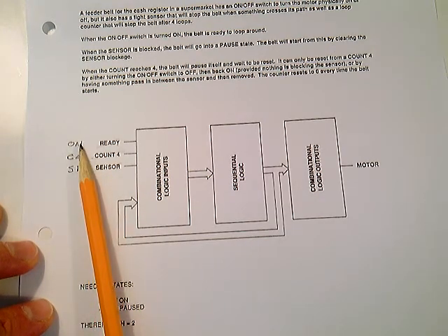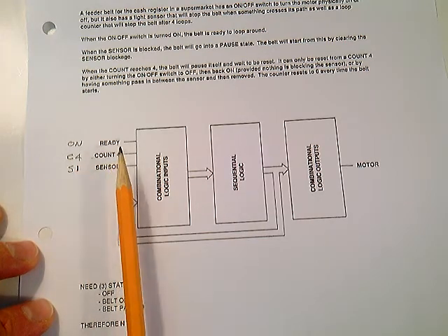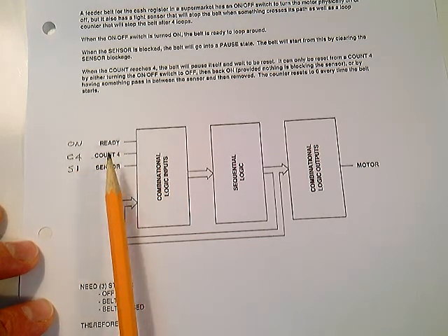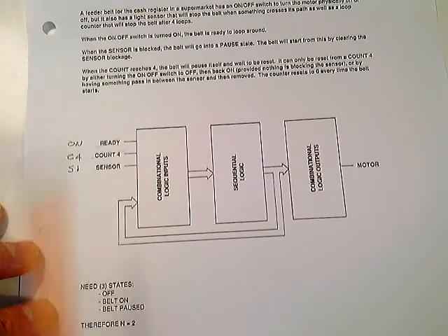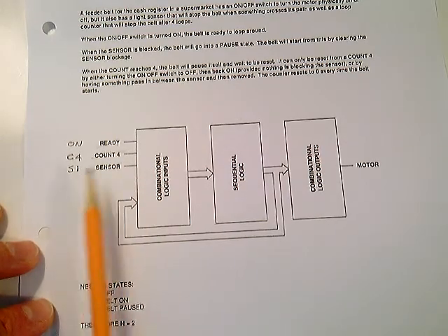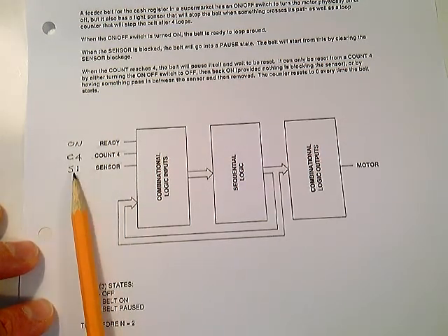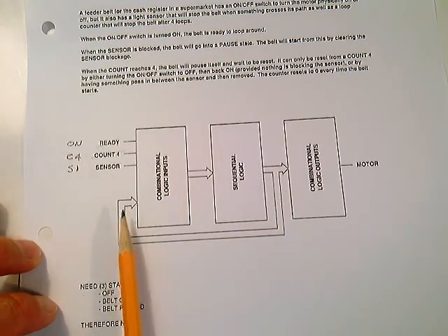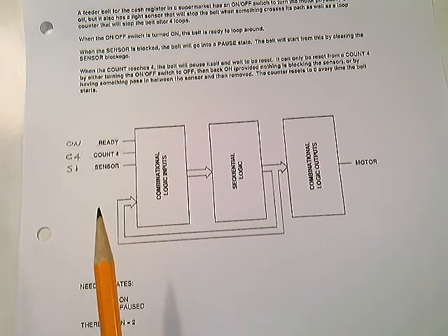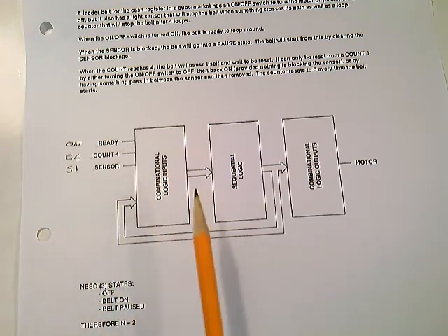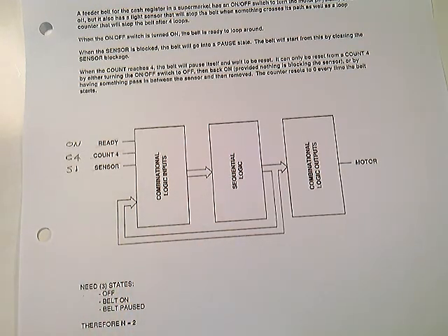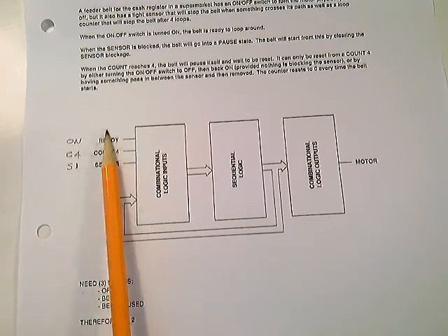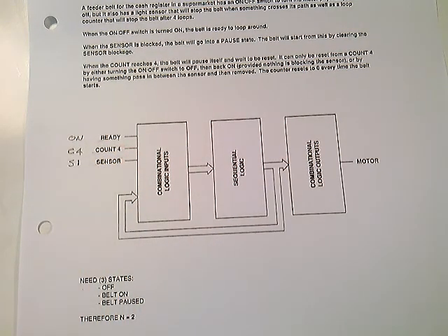On, off on switch, C4, when you're at count 4, and if you read through the spec, you'll know why we have to have a counter there. Tells us we're in count 4. And sensor, and why we have a sensor. Notice we have our 2 feedback terms here. There's 2 feedback terms coming back. So that's going to lead us to a 5 variable K-map. There's going to be 5 total inputs here, 2 flip-flop inputs and 3 asynchronous inputs.